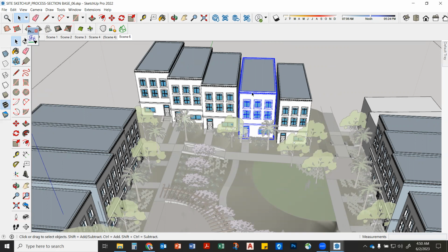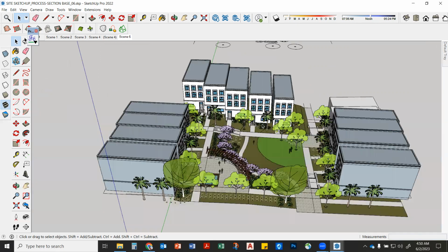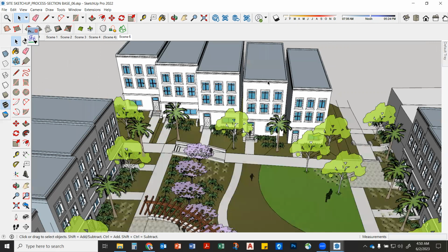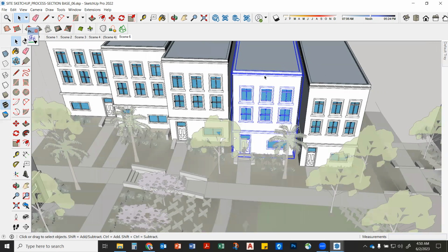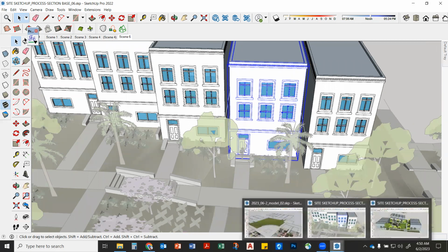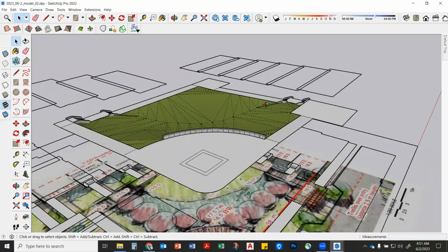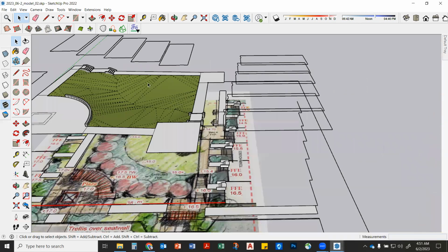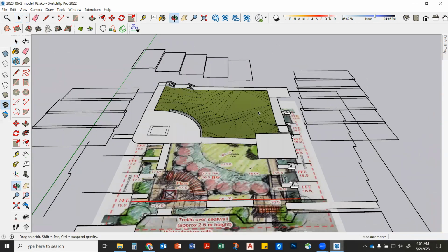Okay. So watch what you're going to do. You're going to find that one. You're going to click in there until you can select just the component, right? This is a component. We're going to hit Control C. Right now, if you come into the other model, you can do edit, paste in place, but it won't actually come into the exact location.